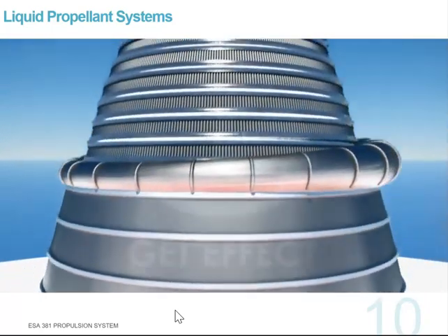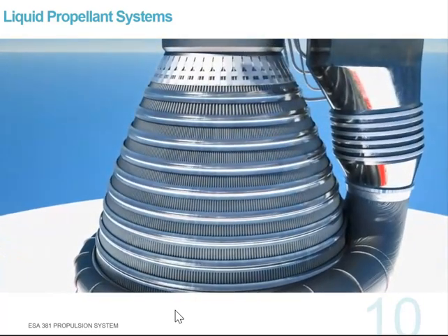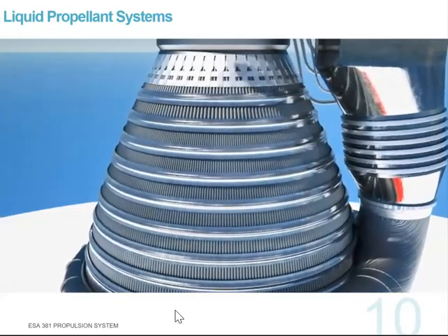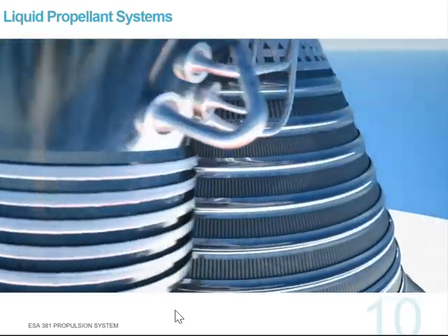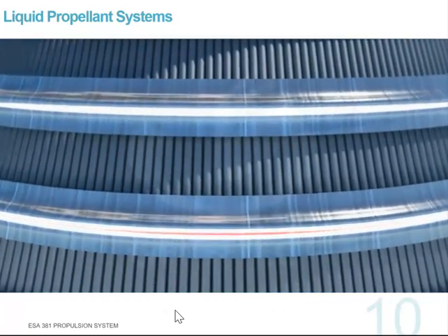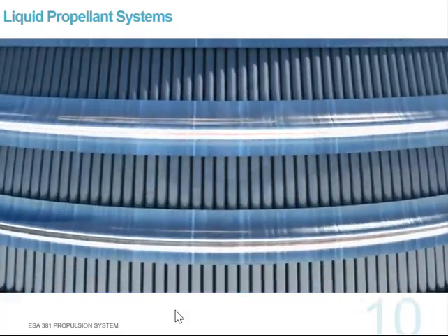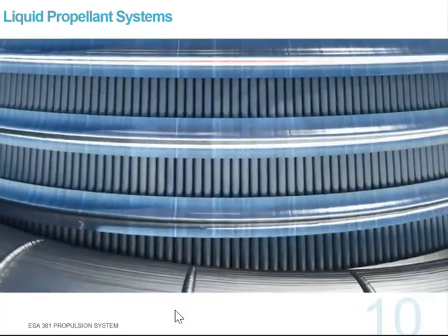To resist the 3,300 degrees Celsius of the combustion gases, the thrust chamber was regeneratively cooled. The wall was made of hundreds of thin-walled, small-diameter hollow tubes, within which the propellant, prior to being injected in the combustion chamber, flowed at high velocity, removing heat by forced convection.